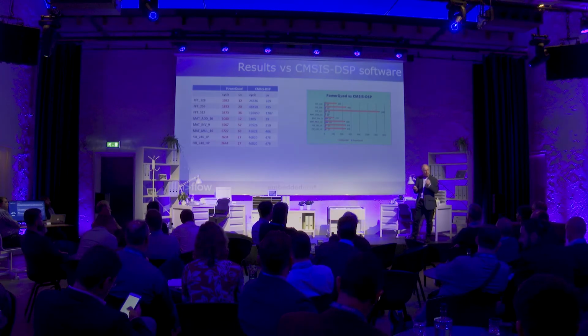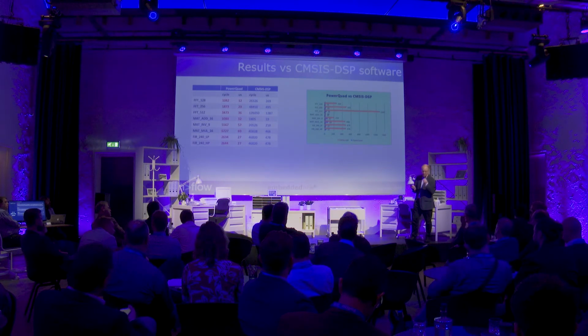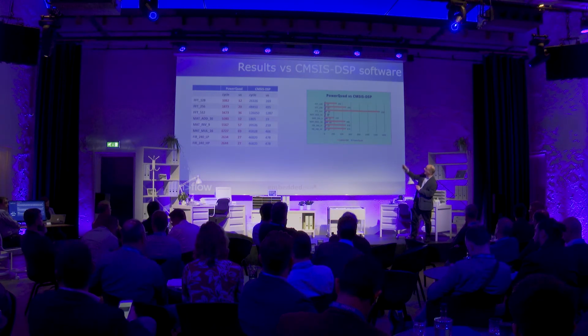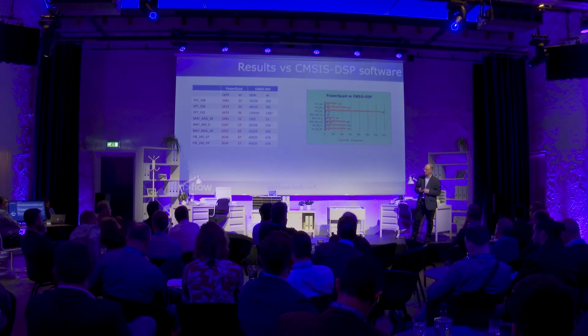So when you're doing kind of filtering on the edge or kind of machine learning on the edge, these DSP algorithms in hardware are a really, really convenient way to get a lot of work done at the least possible current consumption. Of course, there's an adder for the hardware block that's doing all of this kind of accelerated function. But that might be 5 or 10 milliamps compared to the chip running at 48 megahertz for an extra millisecond or 2 milliseconds, where instead you could get back to sleep again.